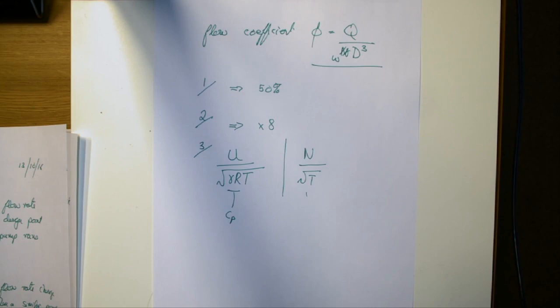In this case, we're now looking at a compressible machine. We're comparing design points on what is otherwise the same turbine. We make the assumption that the non-dimensional rotational speed is going to be constant. And that tells us how the rotational speed must vary with the temperature. It directly follows.